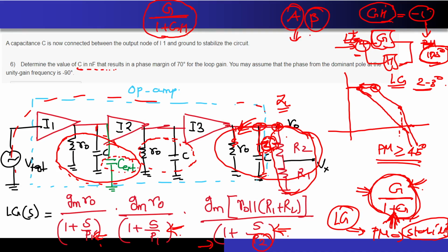Now what you are telling me to do is basically trying to calculate the phase margin of this, correct? So now what will you do after doing this? It will look something like this. I already have a system which is under a feedback. Now if I consider this as a separate block, you want to include one more feedback going like this, correct? So this is what I was trying to say: whatever phase margin analysis you do, you do it for the loop gain first, correct?